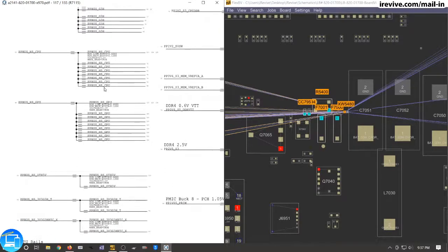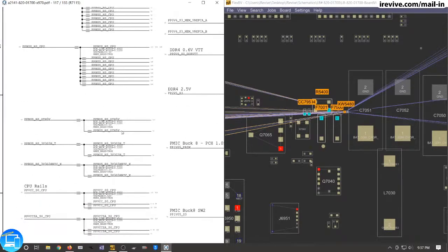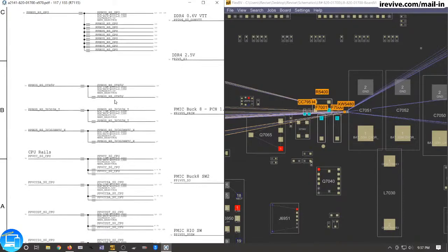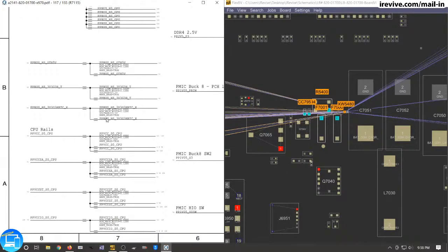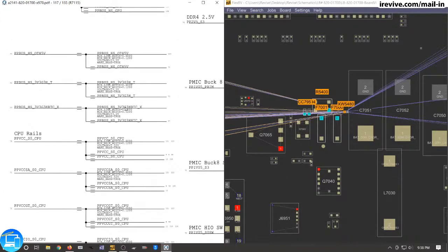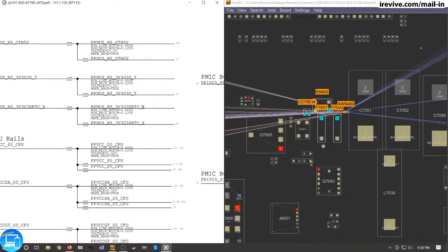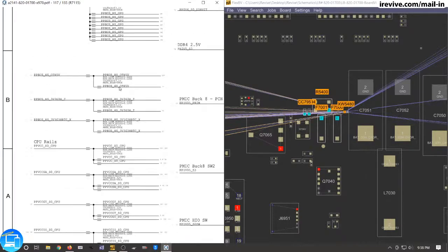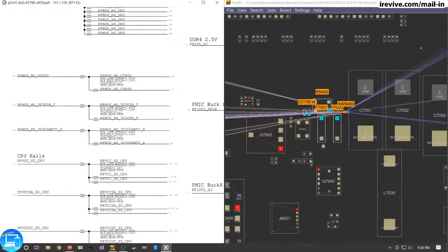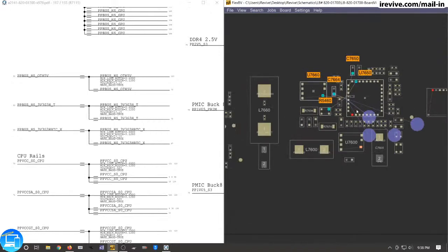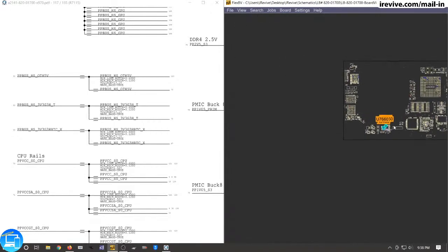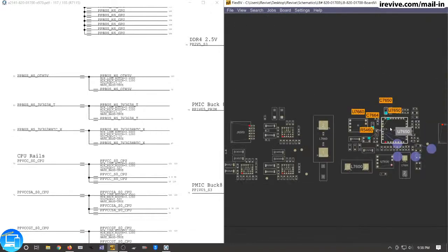All right. Let's look to make sure I'm not missing anything. All this looks like this might be related to PP bus since it's in the name, but this one specifically is also talking about our real-time clock. Actually not too familiar with that line specifically, so let's take a look. It's still the same voltage as PP bus, but let's see what's going on here. So it looks like it's going to be down here on the top side of the board, same side as the CPU.